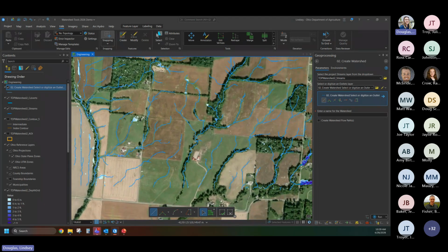That's why I say to use the lower acreage threshold when you're making the stream networks, although, yes, it takes a little bit more time for it to draw all the lines. In some areas, it makes more sense to have more lines, based on the landscape and how many acres are typically coming together in a waterway. So, alrighty, I am going to give this a name and we're going to call it Waterway A.